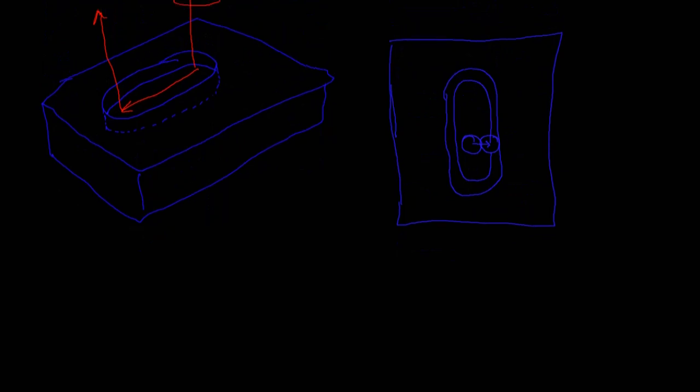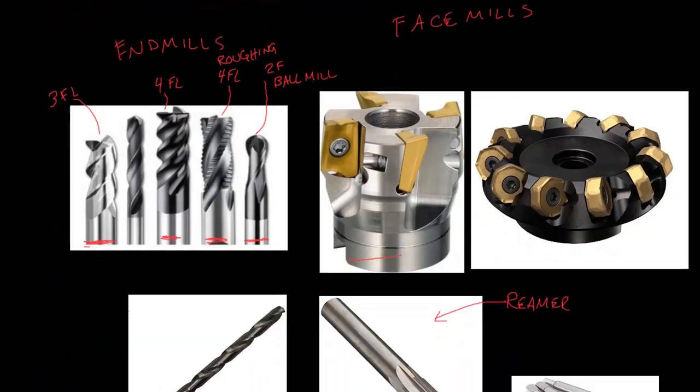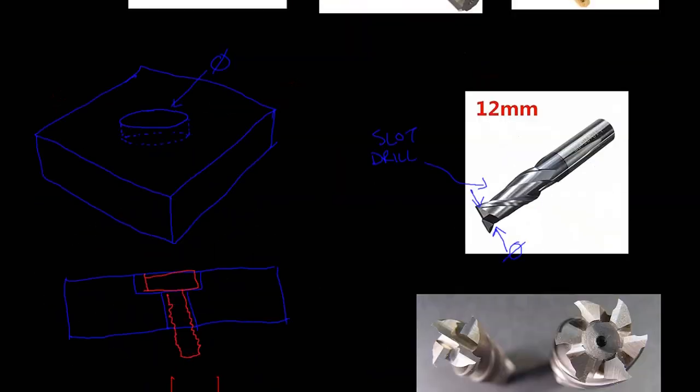So just moving on, I want to talk about this roughing end mill. So what good is this? It's going to leave a terrible edge on your part. Well, if you need to make pockets very quickly and you have a lot of material to get rid of, let's say you have a part that looks like, take up a lot of space on this one.